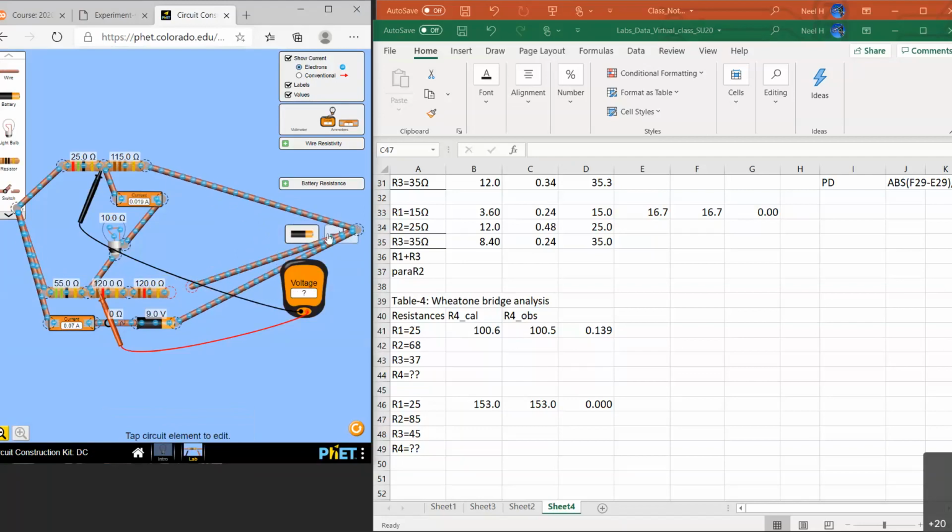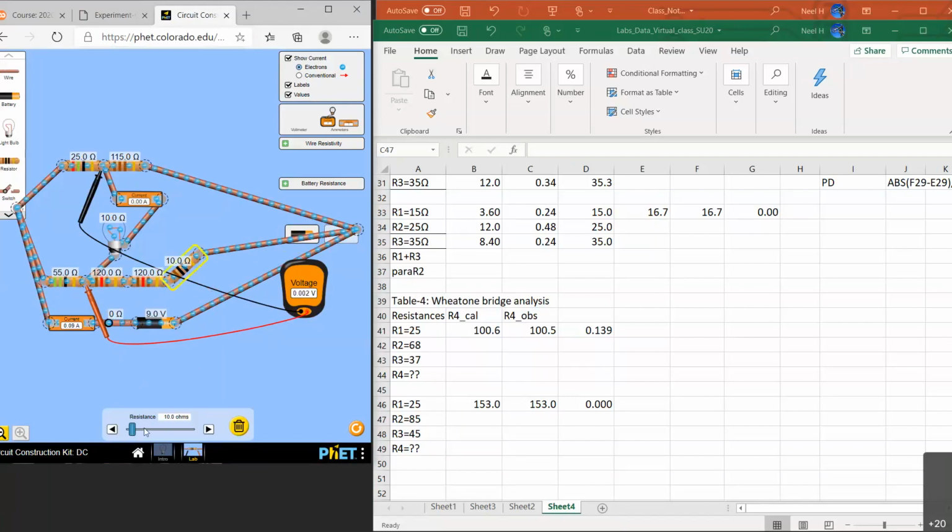So expand this one. Bring another new resistor here, add it serially, and then connect this one. Now your fourth resistor is all of these three together. Change the last one slowly until you see 0. That's the place where we got 0. Adding all of these three together: 120, 120, 240 plus 12, 252. Okay, that's the last one.